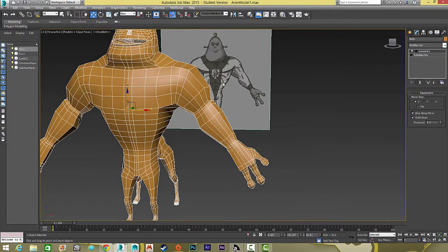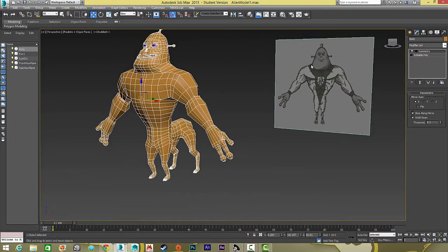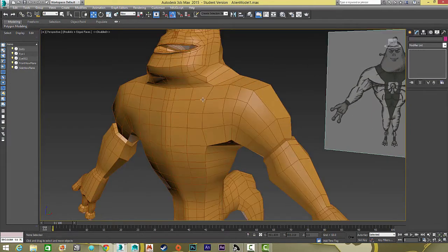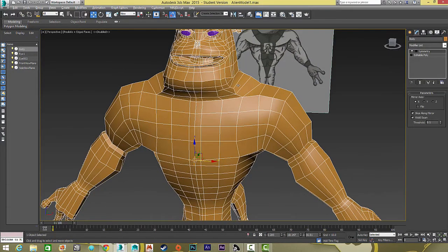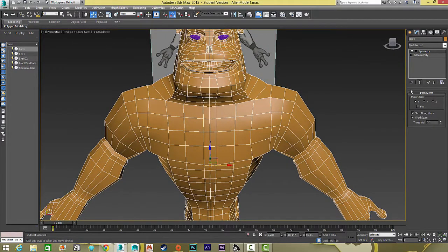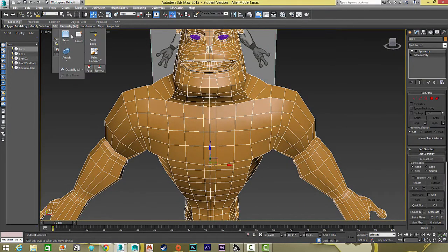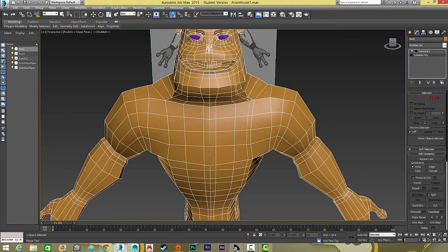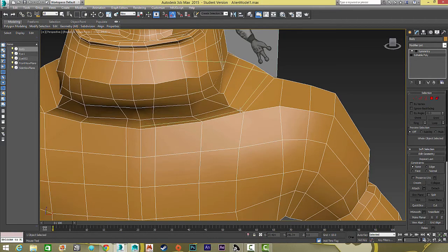Okay, so this character has kind of this big onesie-like suit. It has the clothing all the way up to the neck and then all the way to the appendages where the hands and the feet are. So one easy way to do this is actually to come in here with that loop tool, edit Swift Loop, and then just add another 1 or 2 loops. Just add 2 really close.